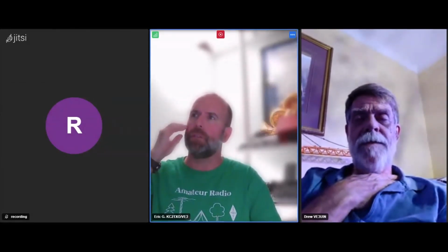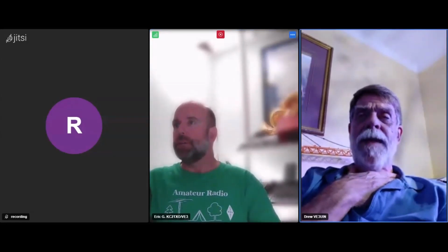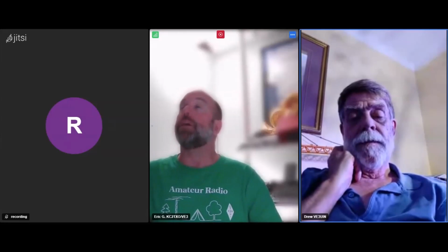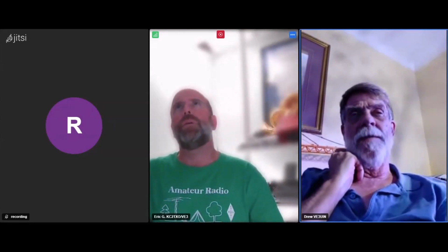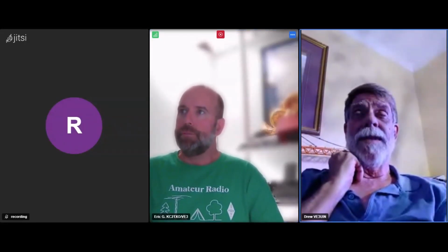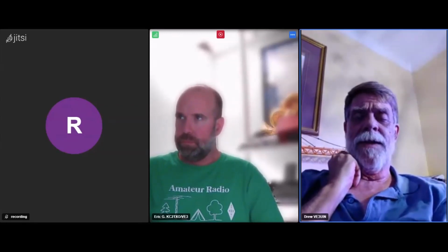Oh, 5 or a bit more, on 13 volts or whatever. I feed it with 3 18650 batteries. So that's about 12 and a bit. I know the True SDX is more tolerant of a slightly higher voltage, but you still have to keep around 12.